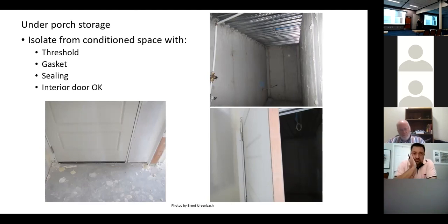Because 2 panes of glass, decent glass with a 1/2 inch airspace gives you around R4, around a 0.25 U factor for the glass itself. So when you use non-conductive materials like these are made out of, it's going to be better than that. So that door is an AHJ decision, but I'm comfortable with that being an interior door. Well, plus I think that's what the code allows. It just calls out a gasket sealed door. Yeah. Threshold. I mean, by assumption, if it's in the thermal envelope, you would think it has to be a 0.32, but it would be better than 0.32.